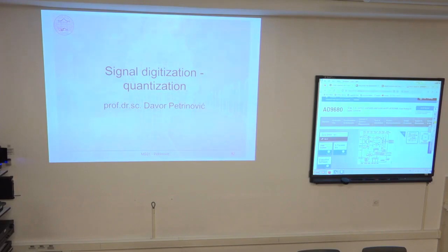If you really need high precision, you must quantize the signal with the highest possible resolution, and it costs a lot. So, for example, the AD converter that is part of this RTL SDR receiver, that costs 20 or 30 euros max, is only 8-bit resolution. So it has a gigasample range, but only 8-bit resolution. But if you want 14 bits of resolution for each sample, then it costs much more.